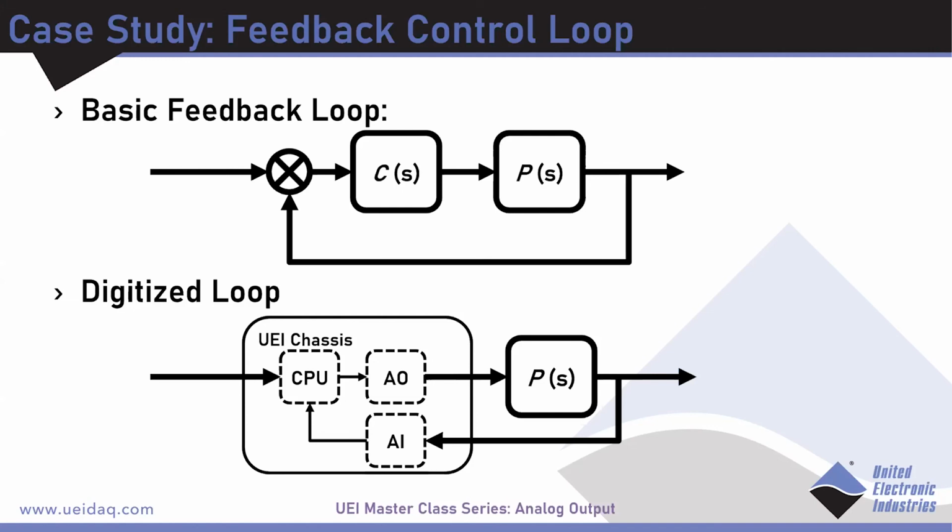Oh, okay. Here's the next question. What happens in case there's a software or CPU glitch or brownout or other, let's say, failure mode? I guess the question here is what happens to the analog outputs. Under the hood, we actually have a watchdog running, so it should force all outputs to 0 volts as a safety precaution. So if your application was a high precision or critical application, that's probably nothing to worry about.